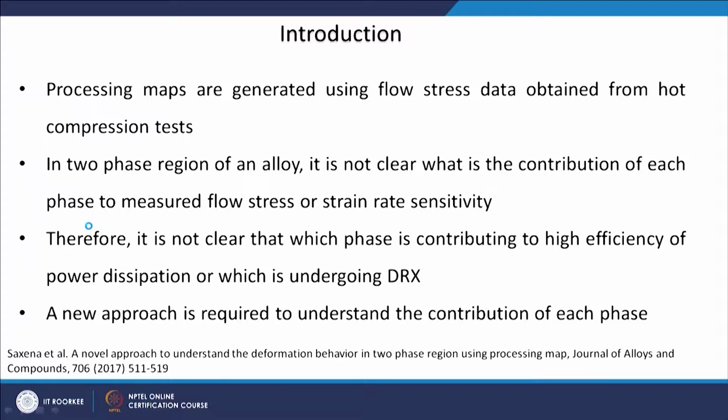But as I have already pointed out, the material behavior is a very important factor in using all these models. And in a two phase material which shows a phase transformation, a simple example is steel: you have the ferrite phase at lower temperature, lower than 725 degrees Celsius.